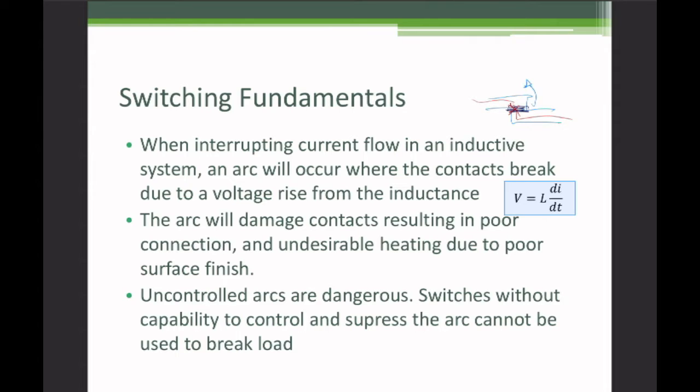The other thing we have to look at is that when we open the switch, there's going to be this arc we're talking about, and how are we going to control that arc? Obviously, if that arc is uncontrolled, that creates a dangerous situation. What if it transfers off of these switch contacts and makes contact with an adjacent conductor? Now you have a traveling arc on the loose, and we saw a video about how devastating that can be in a previous week. So we can't have an uncontrolled arc.